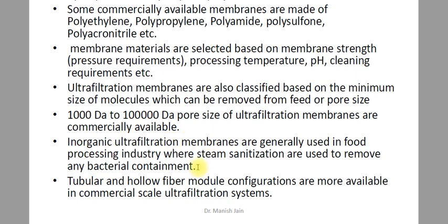Okay, so you have to use the inorganic membrane, generally the ceramic membranes. Now the module configurations used in the ultrafiltration membranes are generally tubular or hollow fiber. Why? Because concentration polarization is generally not a problem in this process.